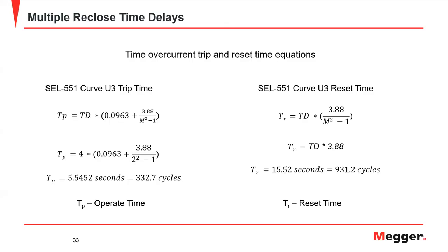Until they dissipate, once you remove all that energy from them, they remain conductive. So if you reclose too quickly and this particle stream still exists where the arc was, then it'll restrike through the same particle stream. You have to give these particles time to blow apart or just dissipate naturally, so they're no longer in close proximity to each other. But it's actually passing through the state of plasma to get there.